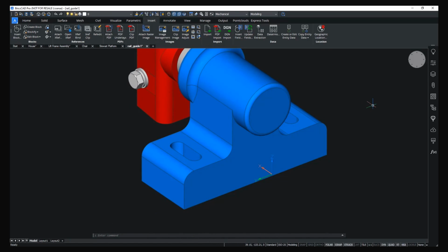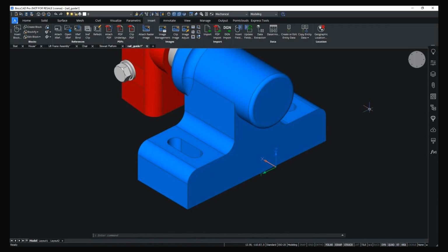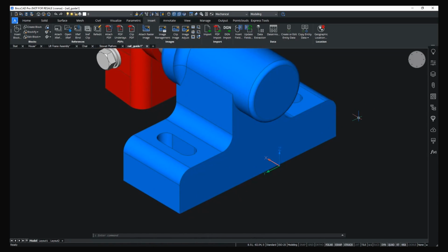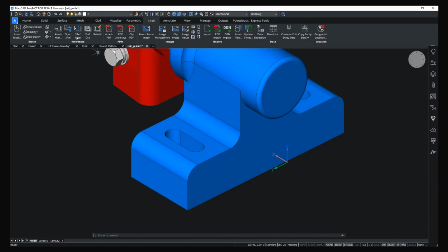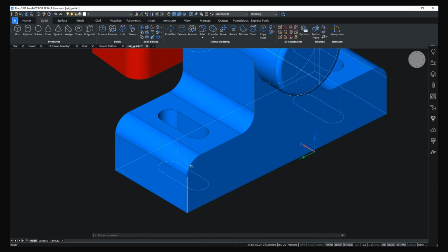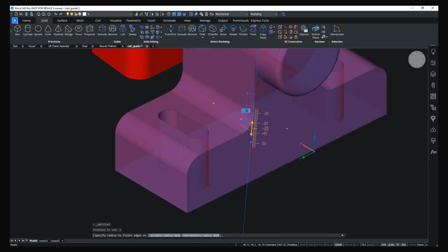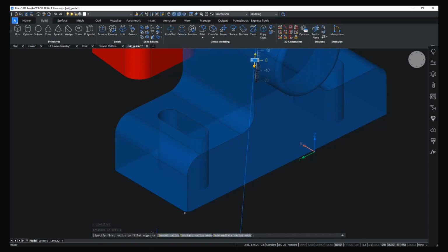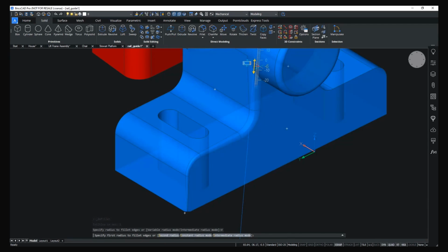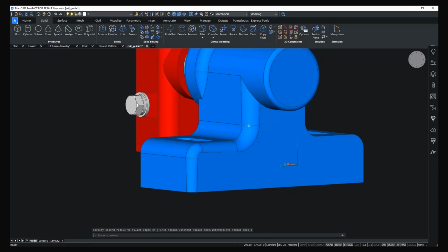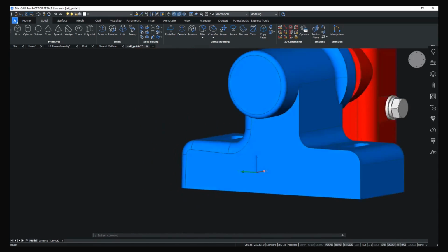When I created the bench, I showed you an example of adding fillets to solids or to edges. But what if we want to create a more complex fillet, like with a varying radius? That's actually all possible. So let me select a chain of edges here. And using the fillet command, I can now choose in the sub options for a variable radius where I can choose between the two endpoints. So I can choose that it goes from 10 millimeters to 5 millimeters on the other end to create a varying radius like this. Or I can go even more complex.